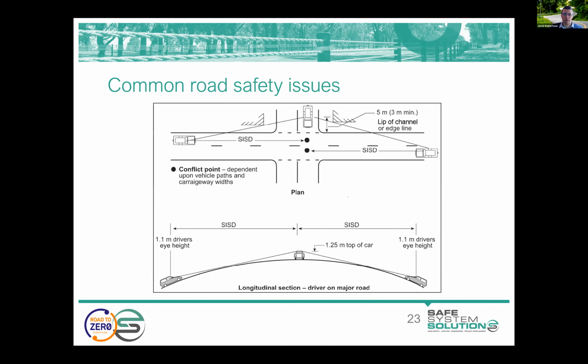So I'd suggest that 3 seconds is probably a little generous, but in the best case, we're perhaps only going to gain, if we're talking about 100 km/h environment, and shaving off 1 second of travel time is only 27 or 28 metres. So in the scheme of 260 or 270 metres that we require in a 100k zone, it helps, but it's not a lot in the scheme of things. The majority of the distance is about deceleration length.